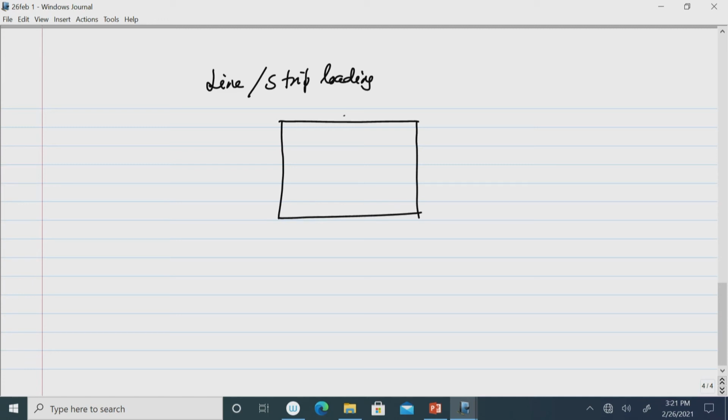Suppose a rectangular plate which is simply supported along all edges, and for example, we have this loading, a brick wall is constructed or any other load which imposes a strip loading, okay, whose intensity is, say, q per unit length, and this line load is imposed at x coordinate xi, and it is running fully along the y coordinate.